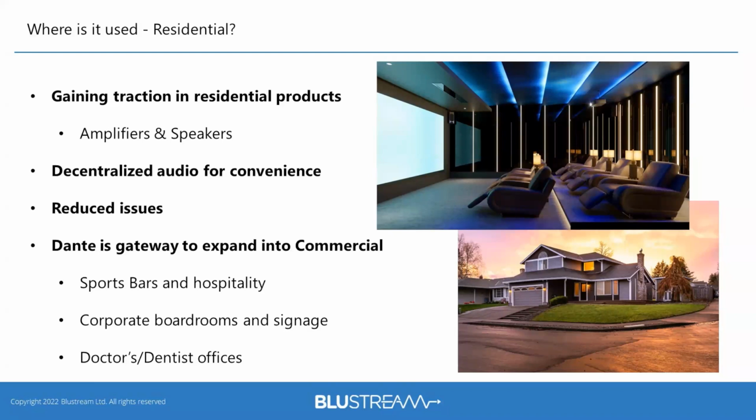They needed the signal replicated and sent to multiple amplifiers where they could tune each woofer separately. The benefit here was the supreme reduction of all the cabling needed to route all of the individual audio signals down to just one single Cat5e cable from the processor to the location where the amplifiers were near each speaker. In this case, Dante was the transport for a full Dolby Atmos theater setup and was also used for the entire house audio distribution system that was located in another area of the house.